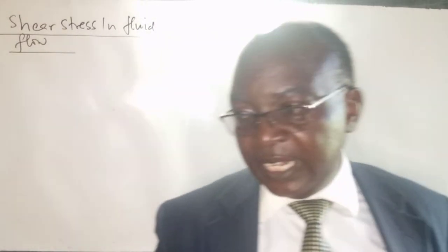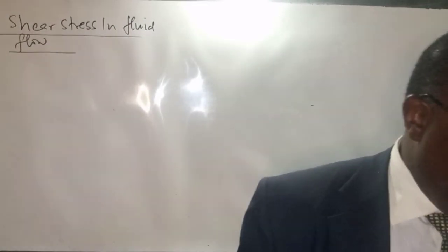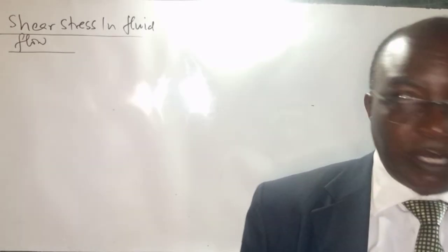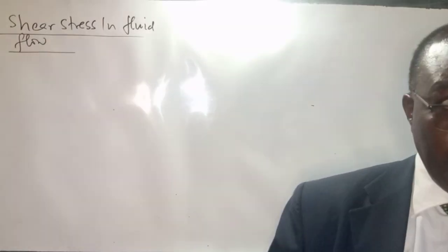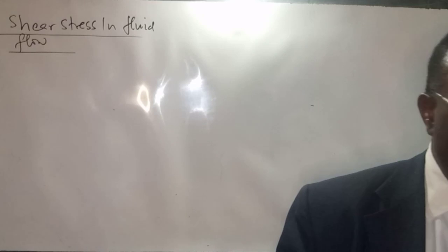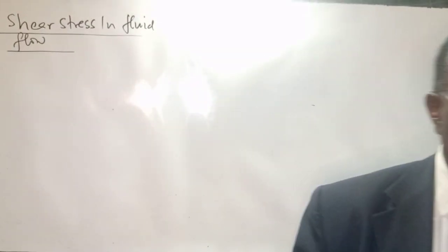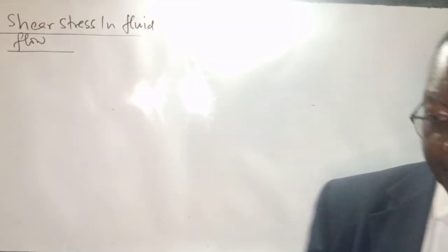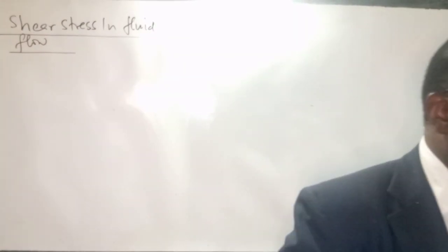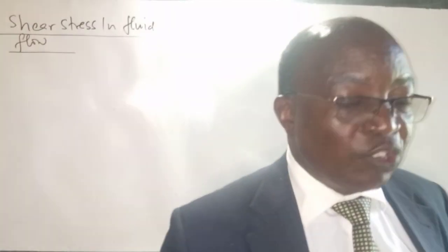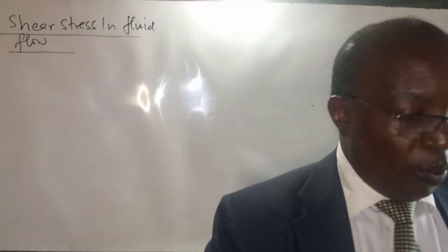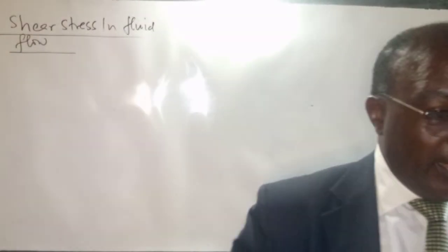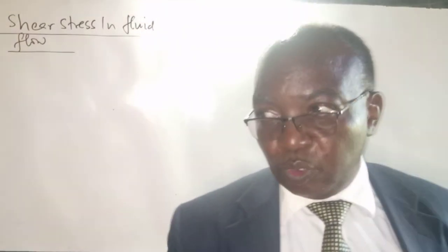And we have looked at the boundary layer patterns or profiles for these particular systems. And when we talked about the turbulent system, remember we talked about the Reynolds decomposition model, where we had the expected value and the varying velocities, because in a turbulent environment, the fluid dynamics are not linear. They are non-linear, and so there is a lot of variation, change in velocity with time, and we say that for the varying ones, the mean is actually zero.